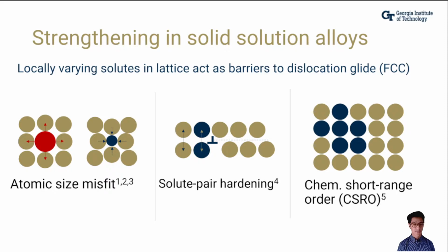Finally, processing methods, such as AM with high thermal or stress gradients, may lead to the clustering or ordering of solutes on the order of a few nanometers, and this is also shown to lend an additional hardening effect. Resolving the atomic level detail of these solute interactions is necessary to adequately describe dislocation-mediated plasticity in multi-component alloy systems.